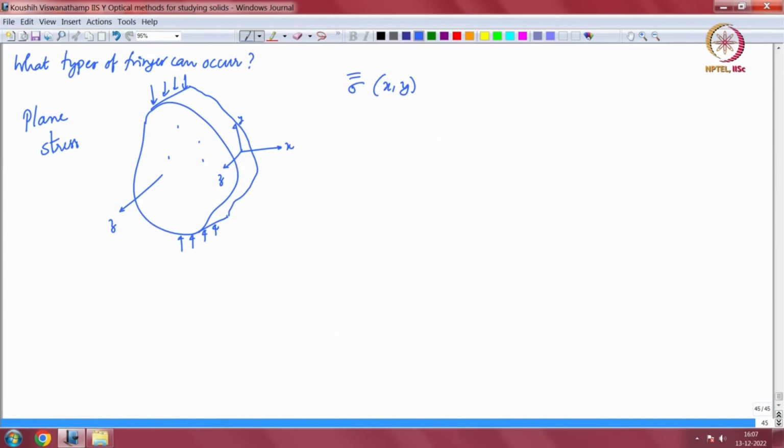and this means that the principal stresses at every point are varying, right, which means sigma 1 minus sigma 2 is also varying from point to point, which means delta is also varying from point to point. So, everywhere in the material depending on the loading you will see a different value for the phase change despite the fact that h and lambda are the same.